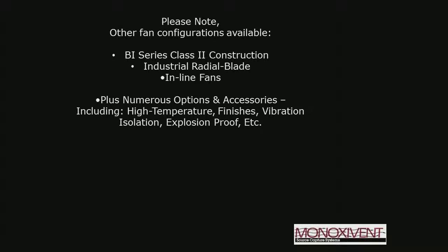We can do optional finishes. Vibration isolation, we have a wide range of those available for these fans, anywhere from just standard rubber and shear all the way up to housed spring and hanging spring if need be. We can do isolation bases if we have to, that type of thing. Explosion proof is an option for many of these fans. We can do from a simple aluminum wheel and a rub ring up to all aluminum construction if we have to, as well as explosion proof motors.